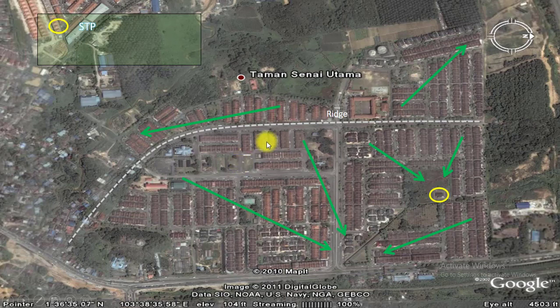So these green lines represent the topography of the land. Using this topography, we must place the sewers. The sewer in this area is heading in this direction. The sewer in this area can be heading this direction, you can see. So this line actually represents like a top hill, a peak point or a summit. And this is the direction, so it's going down here, down over there. So we cannot send all the wastewater directly to the treatment plant, as you can see.